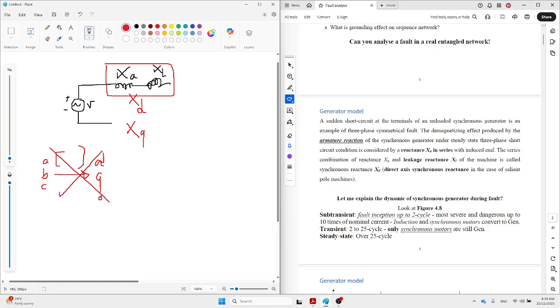Just to know, this is the direct reactance, which we usually refer to. Any X you see in the books or any catalogs is mostly referred to this one. Otherwise, it's very detailed. And XQ is a very small one, so we usually avoid talking about this one.